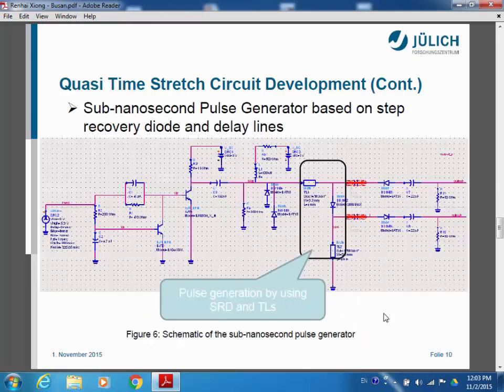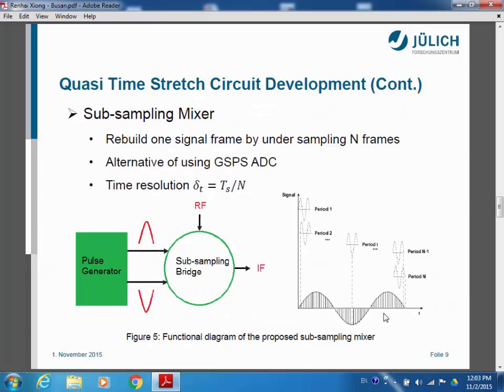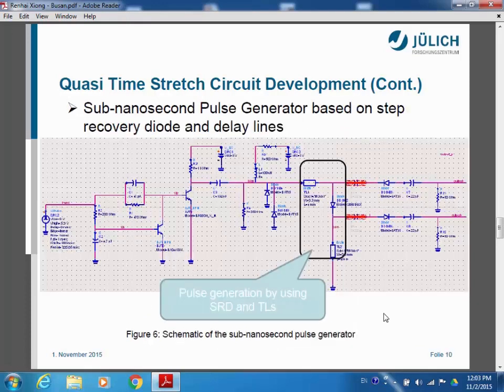We can derive the TDOA and determine the 3D information of the target. One key component is a pulse generator. The pulse generator is used as the gate circuit to turn the ADC on and off to capture the potential level of the signal.